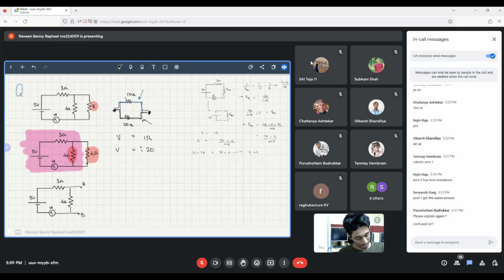Okay, I'm sorry. I assumed that this was trivial, but never mind. So if you solve the equation again, we can see that there's a half ampere current flowing through here using the normal analysis we did. I was going to say, let us see if we get the same thing if we do the Thevenin approach. So if you're going to do the Thevenin approach, first we must find the Thevenin equivalent.